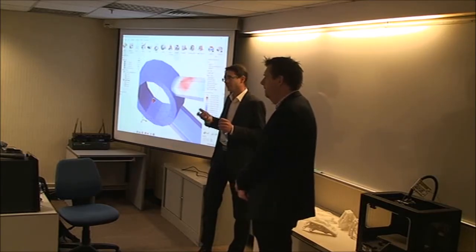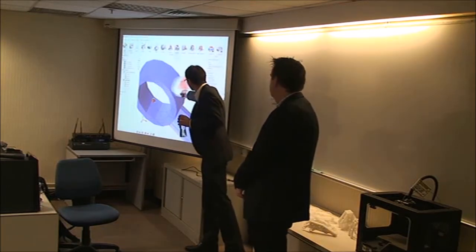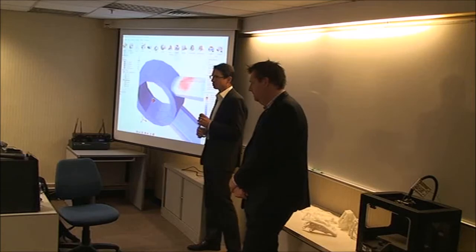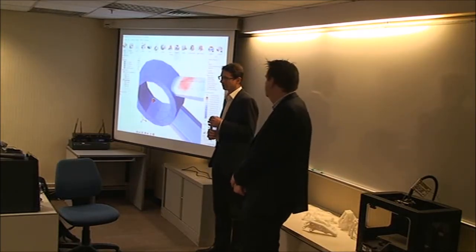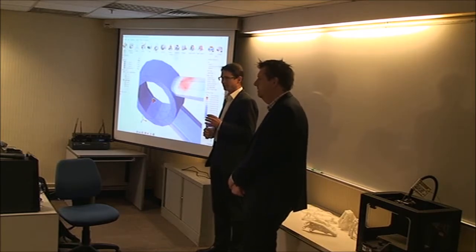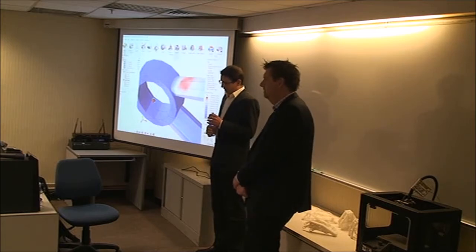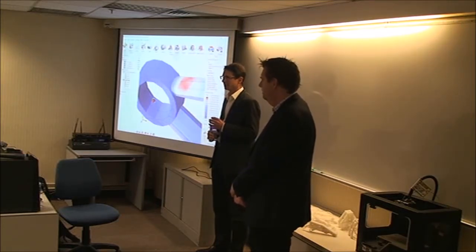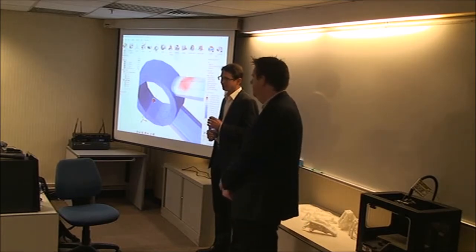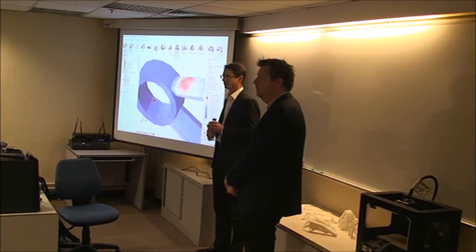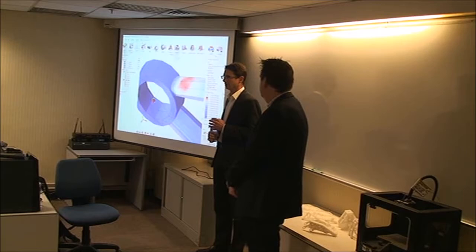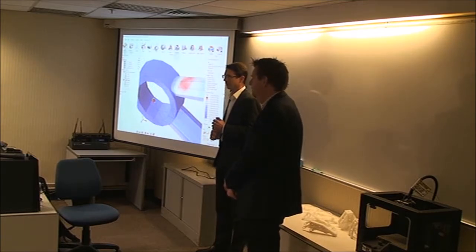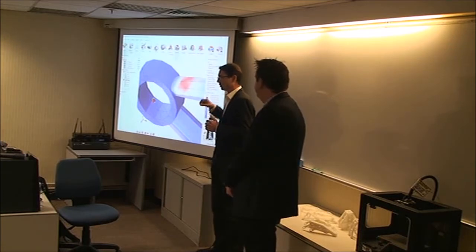X-ray test, I mean, non-destructive testing, of course. You're not allowed to bring any pre-damage into the part. You have to ensure that, and therefore X-ray is one good idea. And the other thing is quality control: you have to certify your manufacturing process, the material you get from the supplier, and the 3D printing machine. All the parameters have to be adjusted and controlled so that you have a repeatable process. Room temperature, and a lot of other parameters, influence the final result. And it all depends on what tolerances you want to go to.